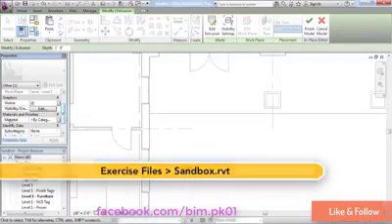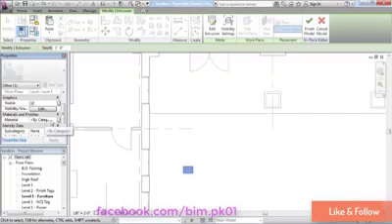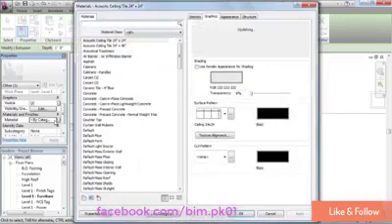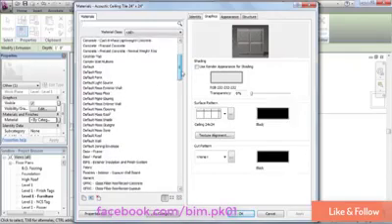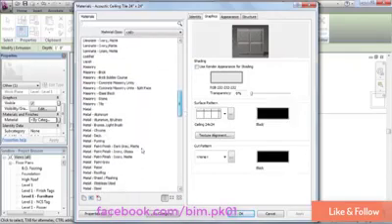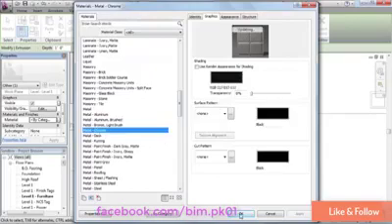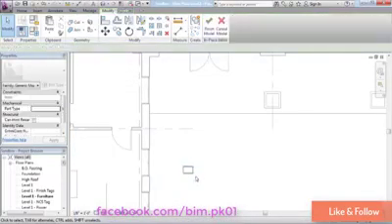Come over here to the Properties palette, and just like we learned in the previous movie, I can click over here in the By Category list, open up, choose a material that I want, like perhaps here under Metals, I can choose Metal Chrome. Select OK, and now I've assigned a chrome material to this box. Now this box is really just a carrier.